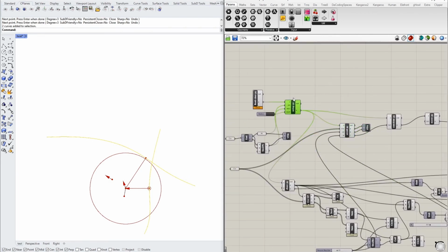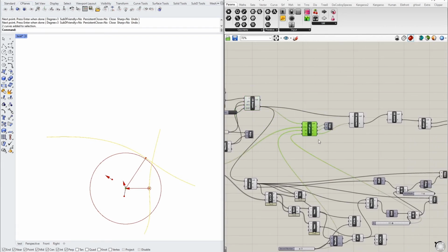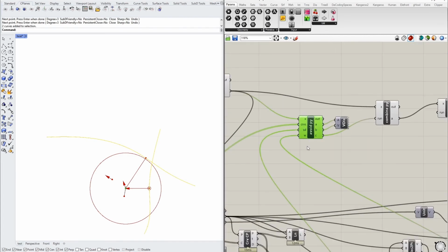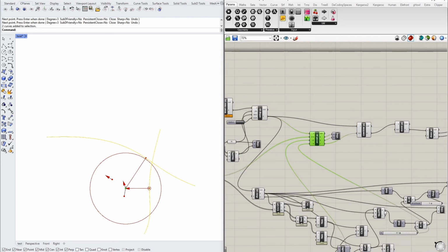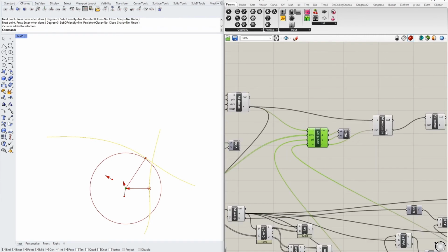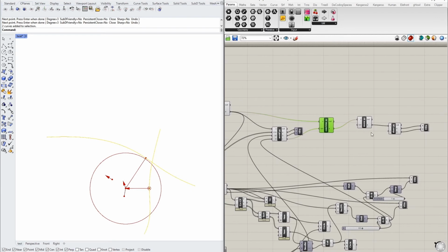So far we have created some instances of the Boids here. So this is the setup, and this is the beginning of the process. So we're going to compute the avoid vector based on some curves, the search radius, and we have specified a specific weighting for this vector of influences. And we have combined it, that is, to add the influence vector with the current direction of the Boid, and we will move it, which is basically the position of the Boid plus the vector, the direction of the Boid.